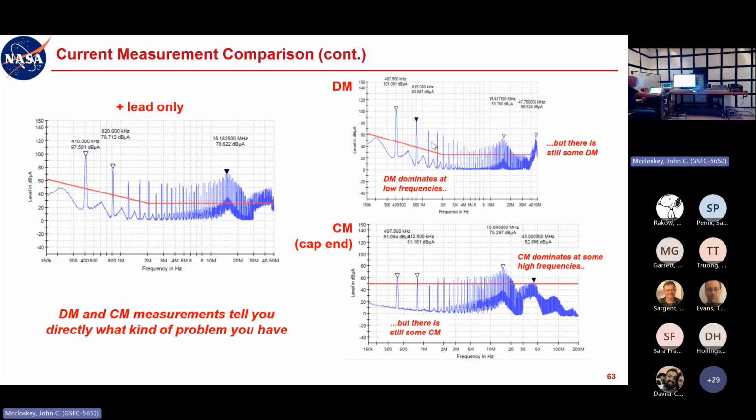When you use one of these converters, this is what you are dealing with. But if you don't see this, then it means that your power converter designer has recognized this and has dealt with it with a tremendous amount of filtering. And so this tells you need both differential mode and common mode filtering, but it also tells you how much of each you need in a given frequency range, right?